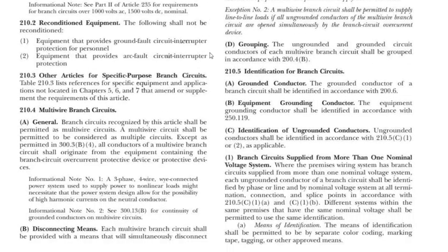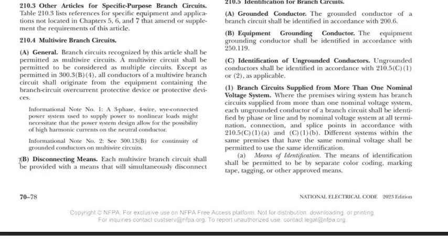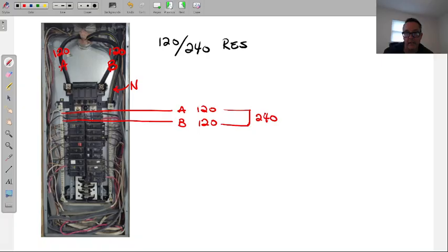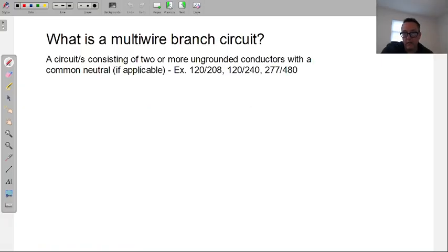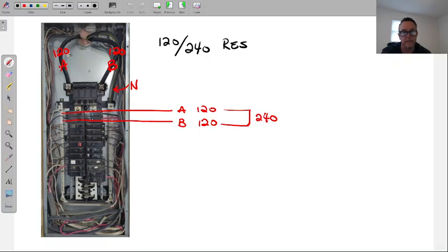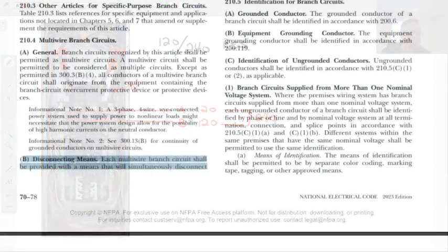And it's actually worth mentioning now as we go into the next bit of this, which is each multi-wire branch circuit. And again, I haven't fully described the multi-wire branch circuit yet, but I've already said, going back over the note, more than one ungrounded conductor means 2, 3 as we get into 3-phase. That's what the more than one is referencing.